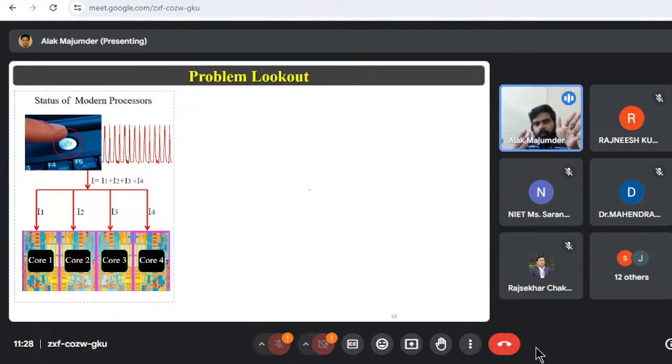Because, for example, the moment we turn our laptop on, until and unless we are opening any application like a Word file, or a PDF file, or a video, or a browser, no activity is happening, which means no core is occupied, right? So what we can do is that at that instant when we are turning it on, we should not give current directly to all the cores. Rather, we can give it one by one. But this timing is very small. It is less than a microsecond. Okay. So that will do the job.